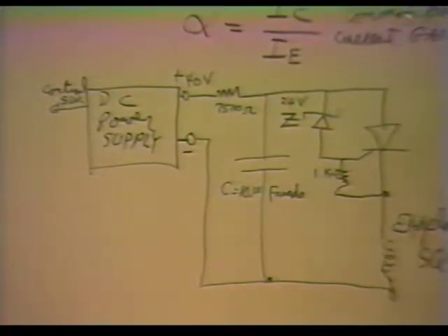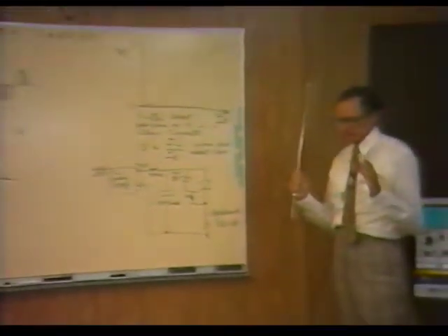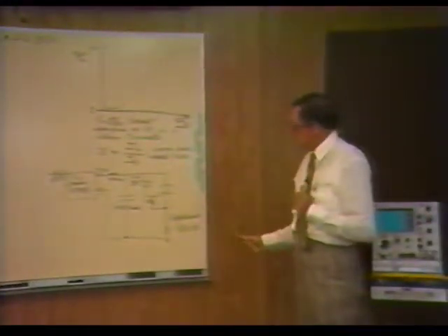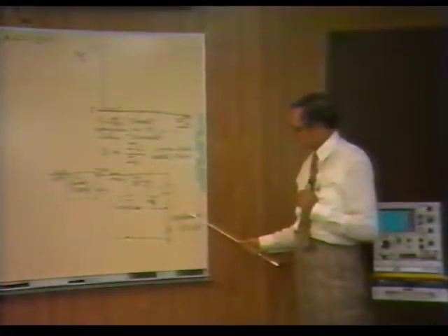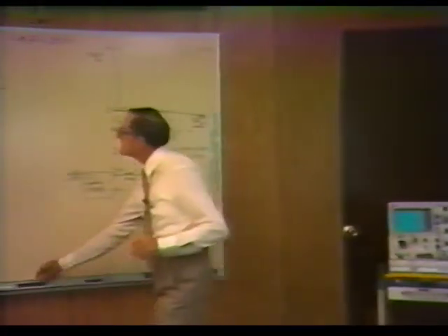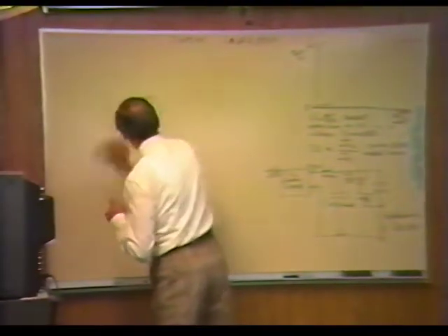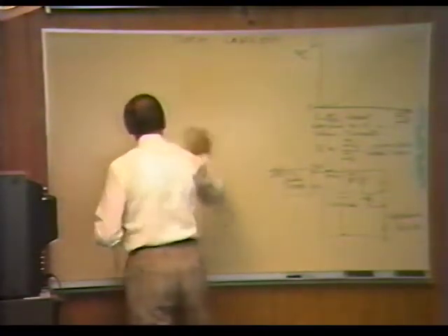What I'm trying to explain with the two circuits I show you here is the fact that an SCR is a device, a switch that has two stable states. An off state in which it blocks, and an on state in which it has a very low path of conductance, the on state. And remember, we're not going to talk about circuits today. We're going to talk about the SCR. So I'll take this off the board now, and we'll start explaining how an SCR does this thing, blocks and conducts. And that's really the main topic of the conversation.